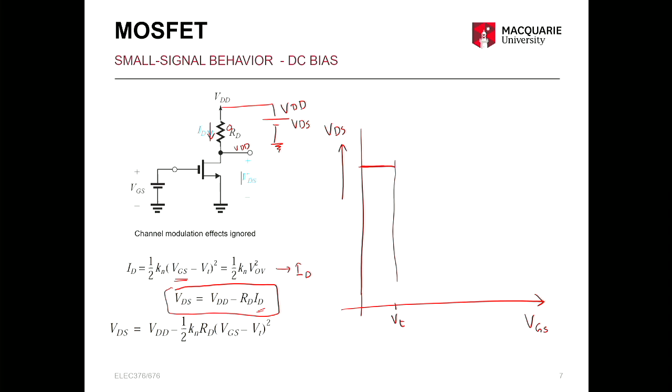So once VGS is more than the threshold voltage, the current will go as a square of the applied VGS. So the output rapidly decreases, because if the current goes as a square of the input voltage, this minus term reduces VDS as the square law, right? It goes much further until the condition reaches here, VDS less than VGS minus VT.